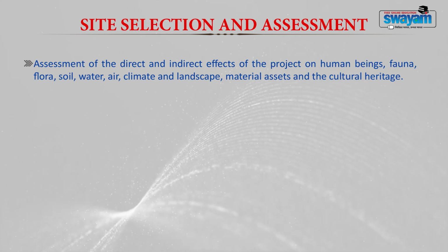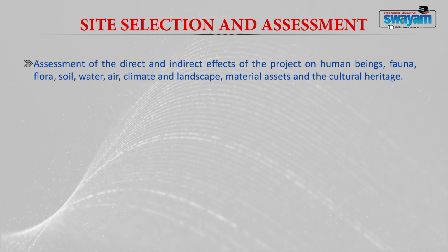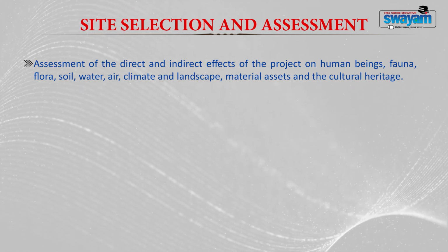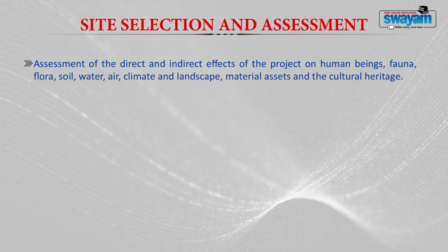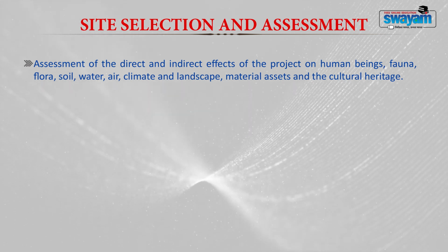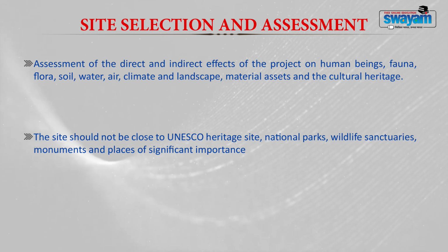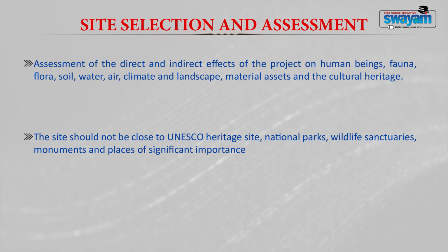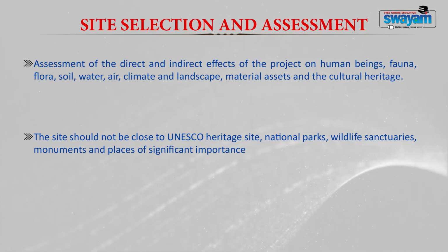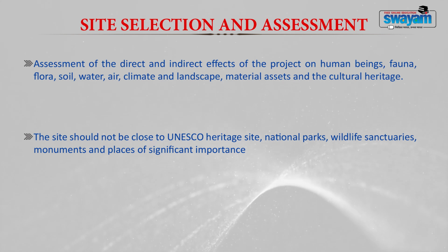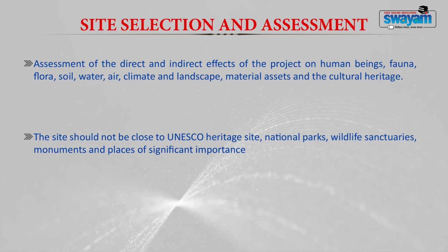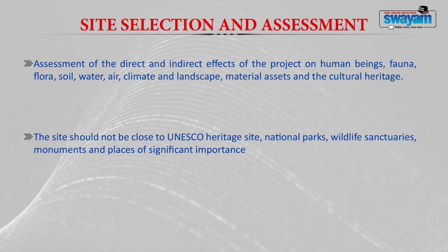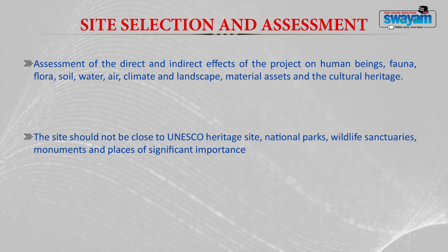Also, you should take care if there is any cultural heritage area around. You should see what impact this particular site is going to create on the environment as well as the ecosystem. The site that you select should always be away from UNESCO heritage sites, national parks, wildlife sanctuaries, monuments and places of significant importance. That means the site which you are selecting for landfill should be away from all these areas. It should not be near wildlife sanctuaries or wildlife corridors, monuments and any UNESCO heritage sites.